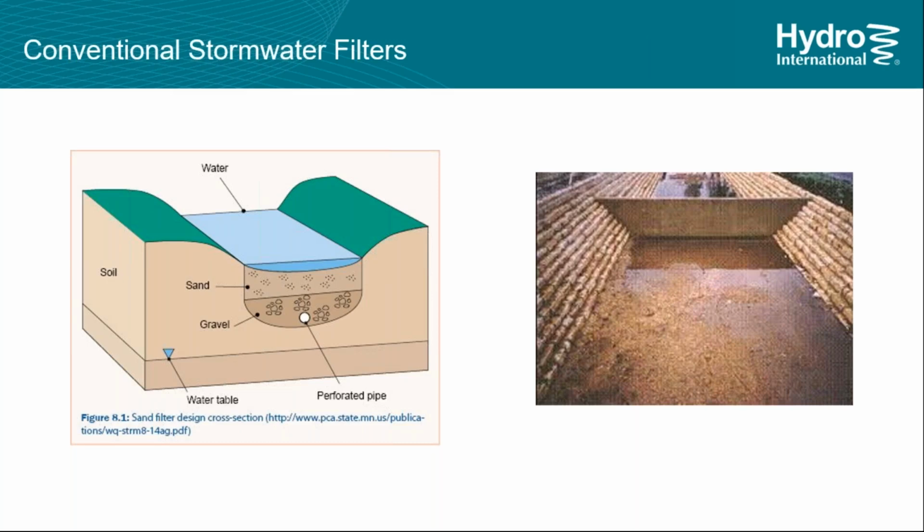Now, the reason why we've moved away from sand filters, even though you'll see them everywhere, is they are above ground and they take up a lot of space and they're quite costly to maintain. So as you're driving by a hotel and there's a large hotel parking area and a large sand filter, if you could have put that filter underground, how many more parking spaces or rooms could you have had on site, which is more revenue for your customer and a better design.